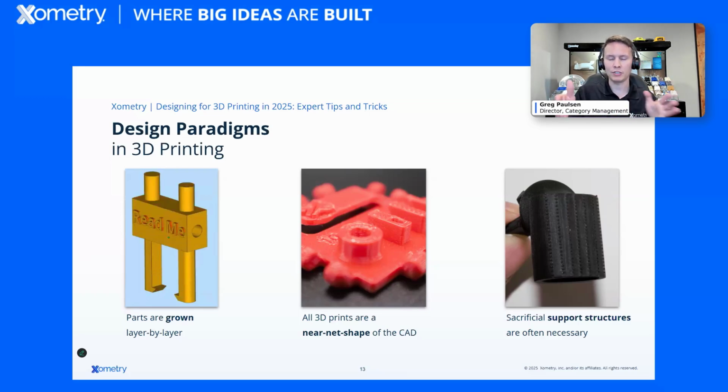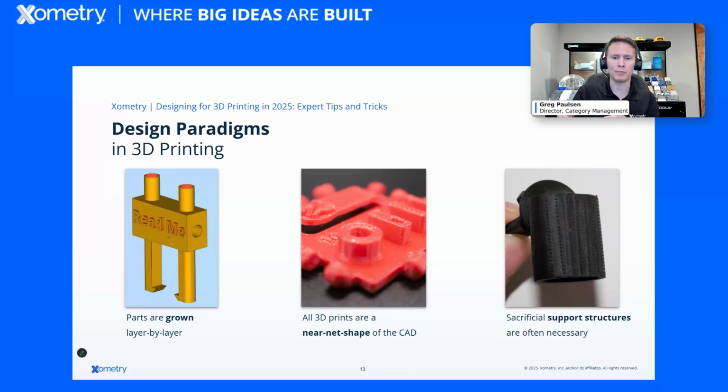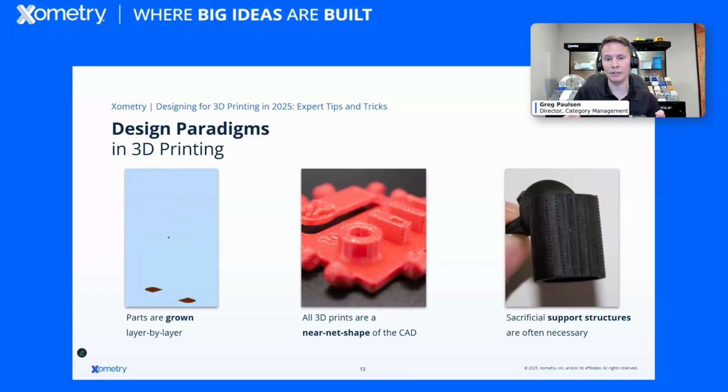In additive manufacturing, the machines are calibrated using essentially calibration pieces, calibration cubes, and then you're producing those parts with standard scale and offsets. There are machines that are more accurate than others, but all of them are considered to be producing a near net shape. And that's important when you think about your tolerances and how you're creating your prints for 3D printing.